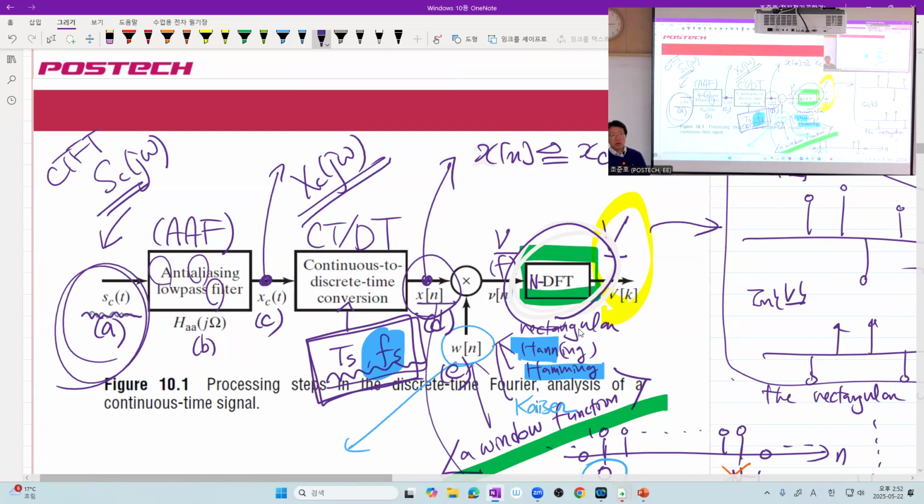So in other words, what if we pad more and more zeros before we perform DFT? Suppose we have cut out L of our samples. Now to make it a length N vector, we pad zeros. If we increase N more, then longer and longer zeros must be padded. What will happen?